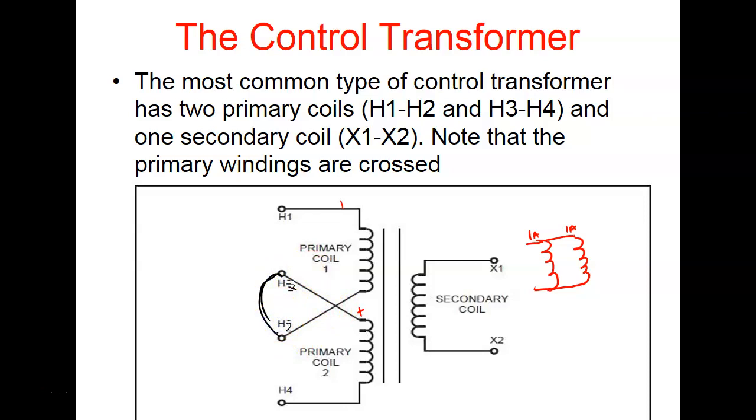So that's why they cross these things, right? You understand that? So now instead of me running wires, I can get these little metal tabs and put it across the center two if I want to divide by 4, or put it across the outside if I want to divide by 2. This is the 12. So I'd put it across the center one if I wanted to divide by 12. I'd put it across the two outside if I wanted to divide by 6. Ours is going to be a divide by 4, divide by 2, and we're going to do it purposely. We're not going to change the voltage.